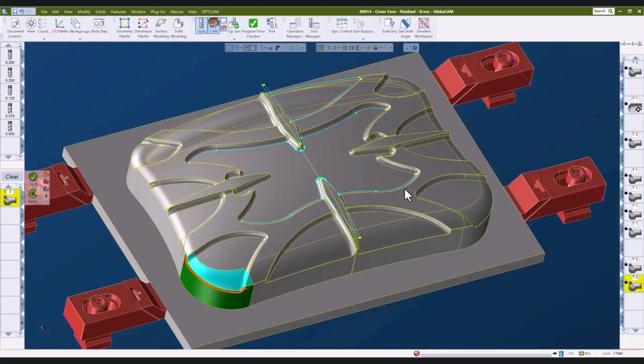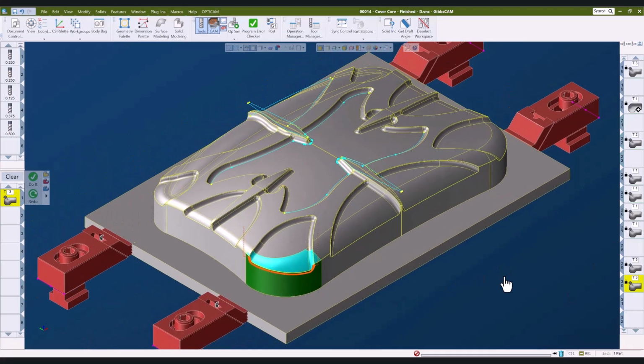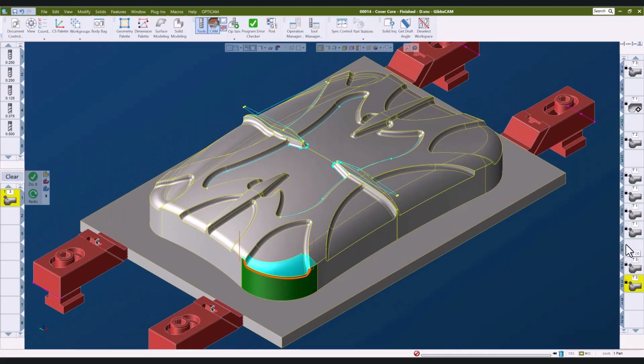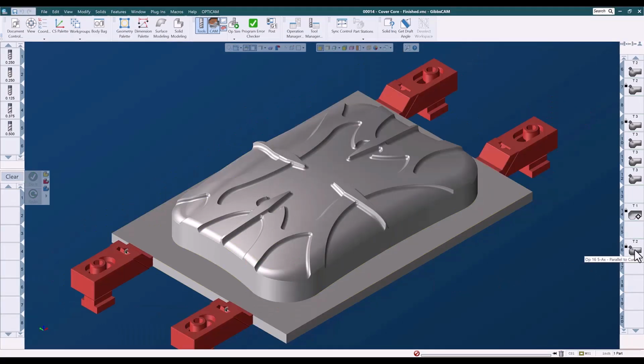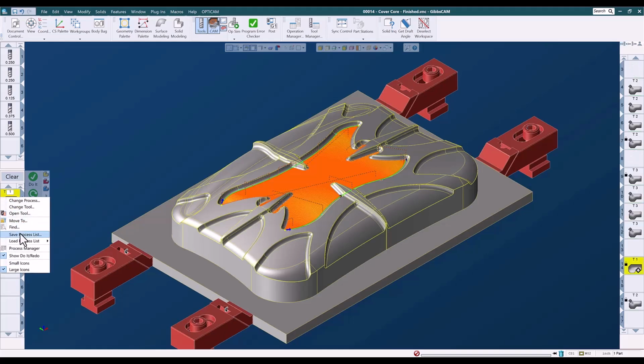Now, once we've developed toolpaths, especially if they're well suited to the parts we commonly manufacture, it can be really helpful to save the processes. Let me load this one up again. This is an advanced 3D in-curve flow using a 1/4-inch ball mill and with a step over of 20 thousandths. If I think this did a really good job on this part, and I'm likely to use this strategy with the same tool on something else, I might want to save the process. Then I can call it up anytime I need it with just a couple of mouse clicks.